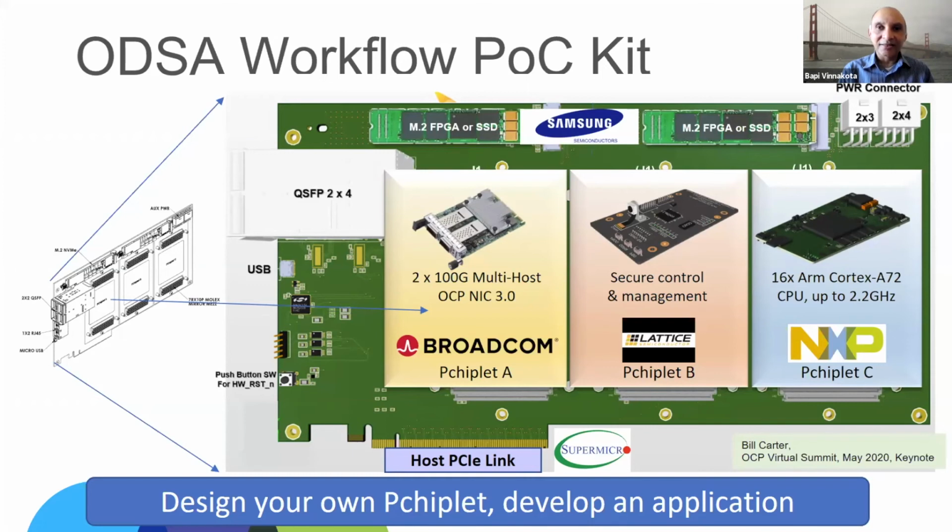It turns out really mundane things turn out to be hard, right? Each part typically may have its own memory interface. How do you sequence power to these guys? How many different power supply rails do you get? How do you get everybody aligned on a common management bus? How do you sequence operation? How do you do presence detection? How do you automatically know whether the board exists? So there's a whole bunch of just mundane logistical problems in my mind that package designers face, that if you could somehow standardize those, there would be a lot of value in making design turnaround much, much faster.